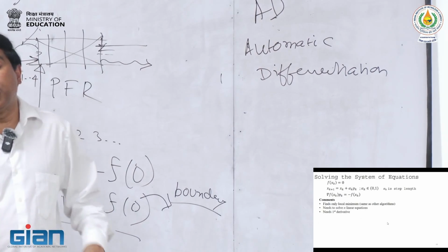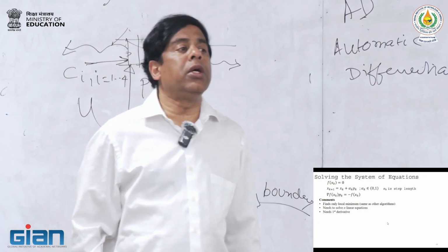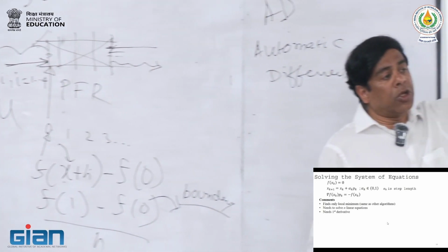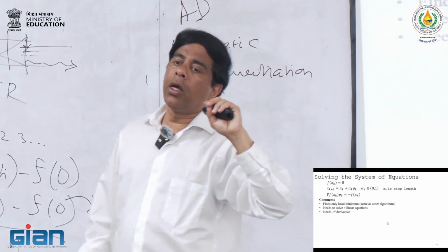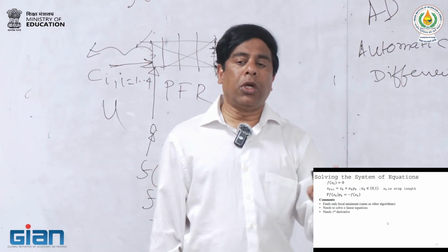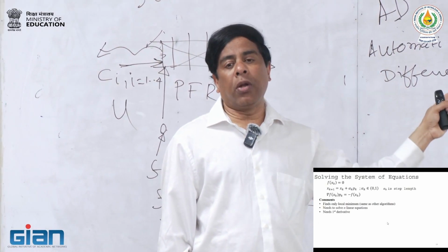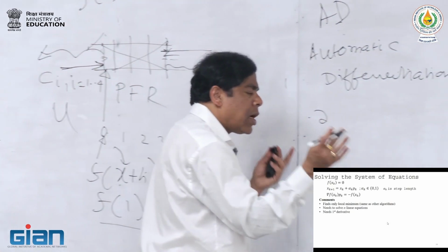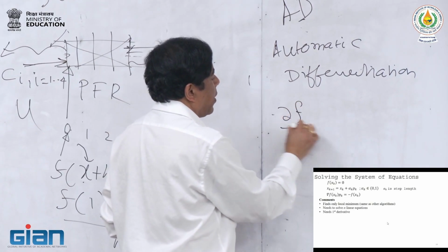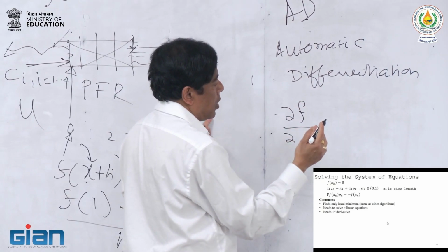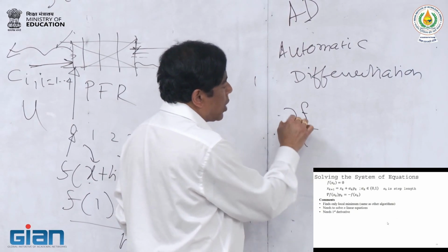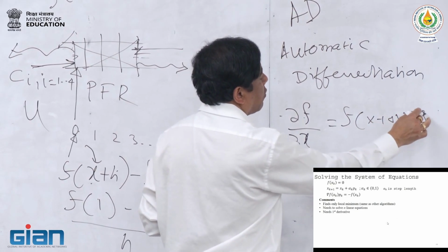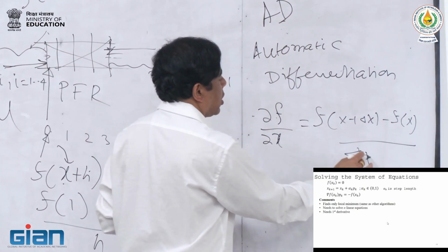Aspen still considers derivatives to be numerical derivative calculations. So all the Jacobian calculations are considered to be only numerical based. It basically comes from the fundamental properties: if I'm trying to calculate this derivative, I'm simply saying f of x plus delta x minus f of x, and then dividing by delta x.